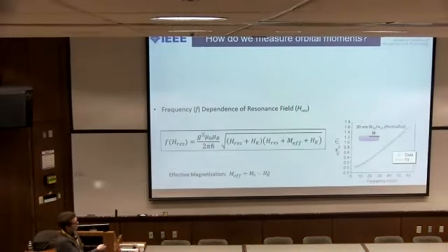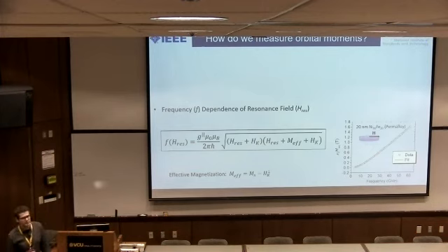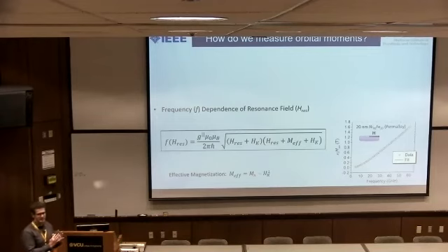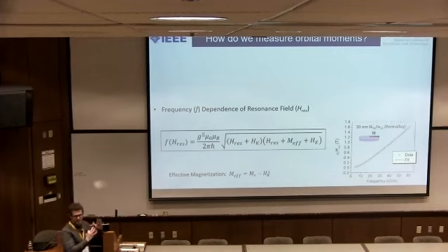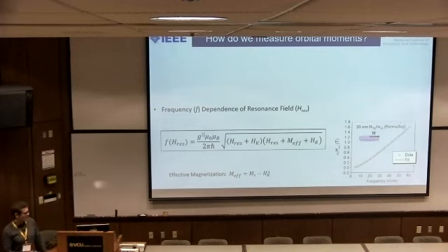Right, you can see how we're measuring all the way out to 60 gigahertz, and we don't see any wiggles, so to speak, in this particular case. It's a different sample, I understand, but the point is this is not as susceptible, because this is spectroscopic, right? This is a position of a peak. Measuring the width or the amplitude is not a spectroscopy. You're not measuring just a frequency, right? You're measuring some width or amplitude or something. That's where errors start to come in, and differences in your microwave circuit come into play more significantly.